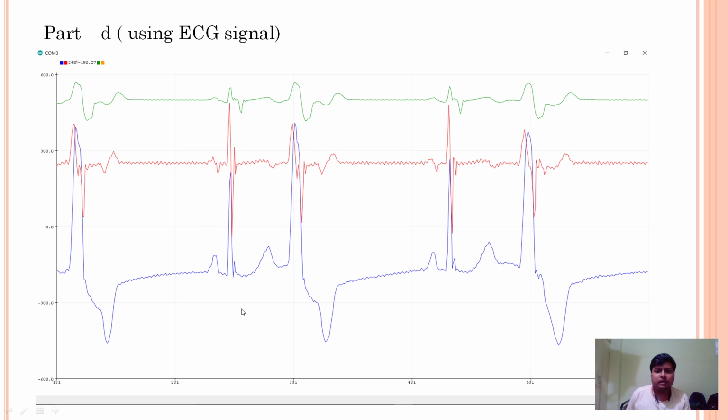As you can see, wherever there is a high peak, we also get a higher value at the first order derivative filter, which is the very function of this derivative filter. And finally, we smoothen out the signal using the moving average filter with window value 8. And we can see as we smoothen out the signal, this peak basically gets a normalized value.